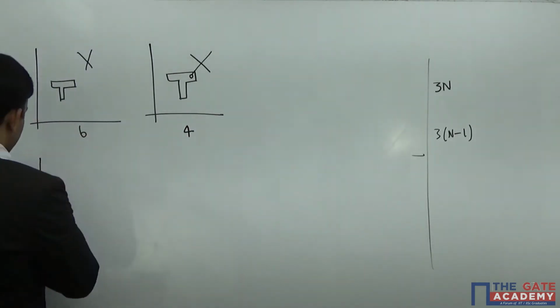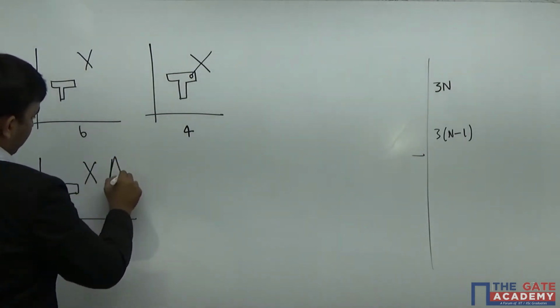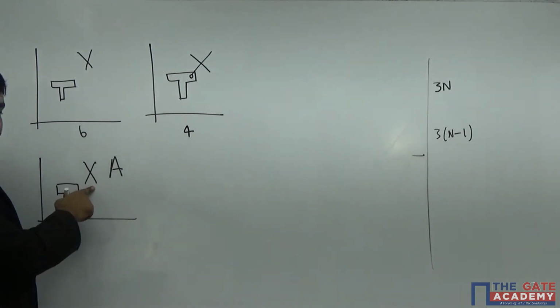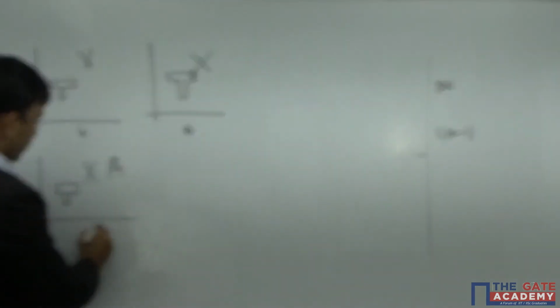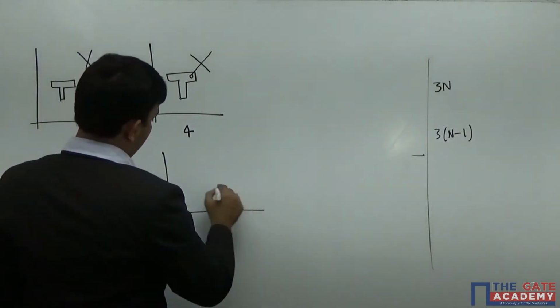Now see here, if the system has 3 elements like this, to describe position and motion of each element I need 3 parameters. For this one, I need 3 parameters. I can say degrees of freedom of this one is 9. So if I establish a connection with the help of a lower pair,